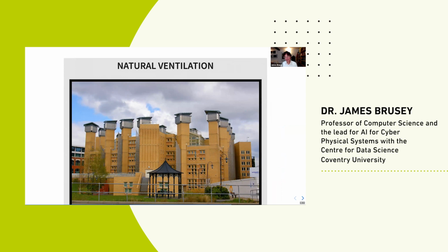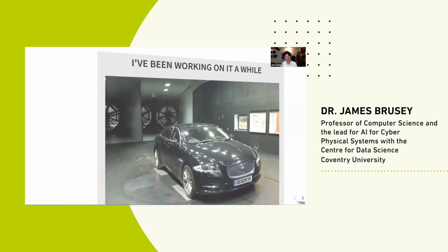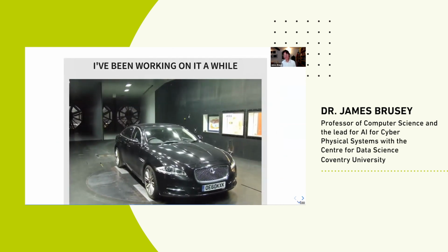But also the idea is coming from Australia, I think, where they tend to make use of natural ventilation to use external air to cool the building down up to a certain temperature, and then they close windows and start running the air conditioning system only when it's very hot. And it's obviously an opportunity for saving energy.